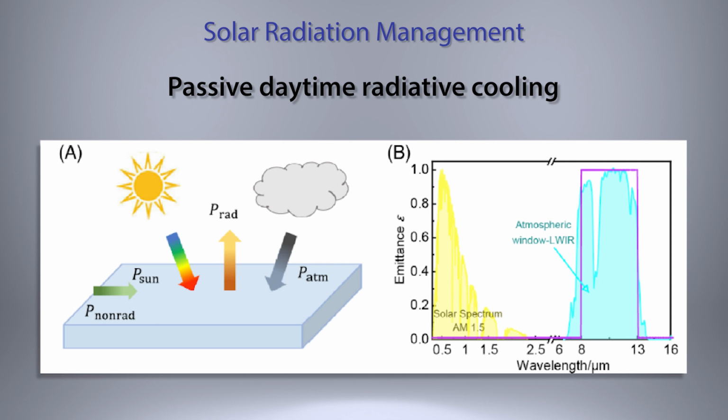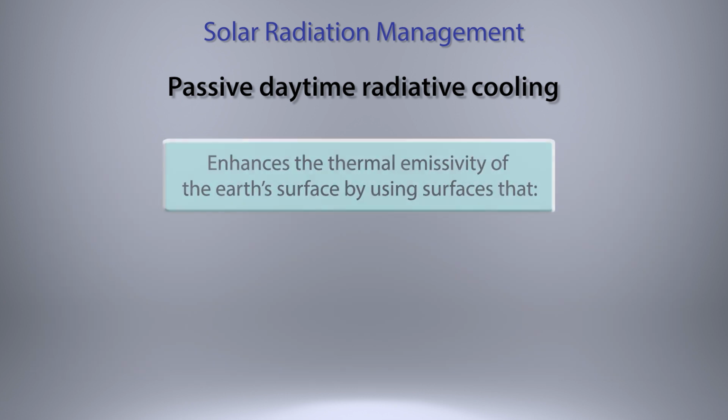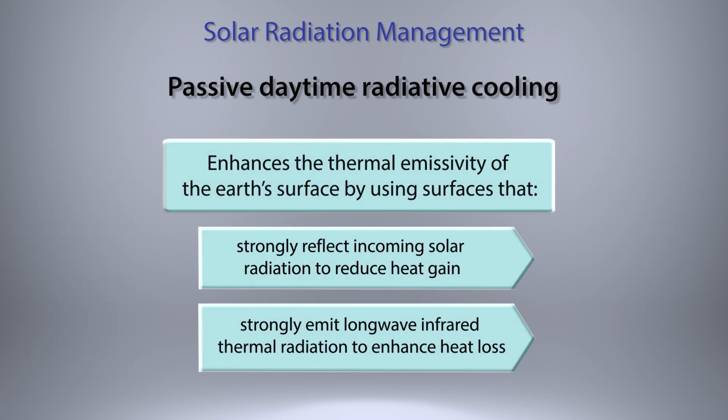Now I know that at night it tends to cool off, and that is because you don't have any more incoming energy from the sun, but the bodies which heat up during the day will re-radiate in the infrared part of the spectrum. So the goal here is to reduce the incoming radiation in the ultraviolet and the visible part of the spectrum, and then increase the re-radiation in the infrared. And that can be done using certain materials, which I show on the next slide.